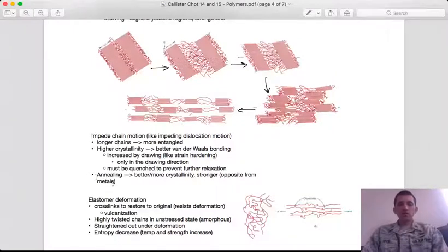If you bring it up to a high enough temperature where the atoms can start to move a little bit more, but yet you haven't changed the phase and reset the microstructure, in metal systems the atoms will move in such a way that they reduce the energy and heal dislocations and remove crystal lattice strain, and all of that leads to more ductility and less strength.